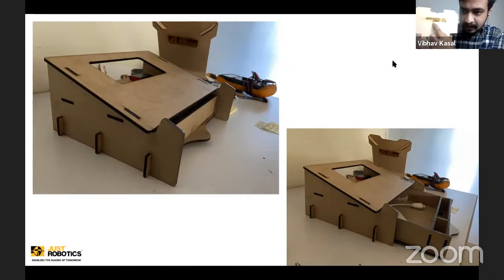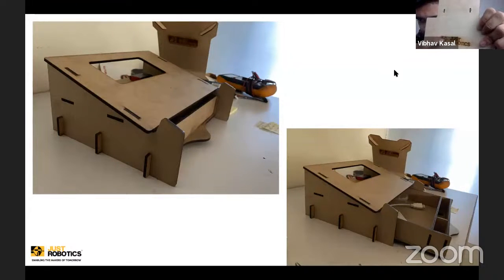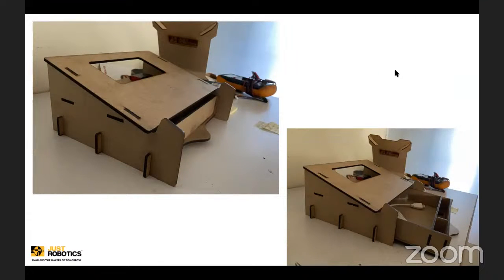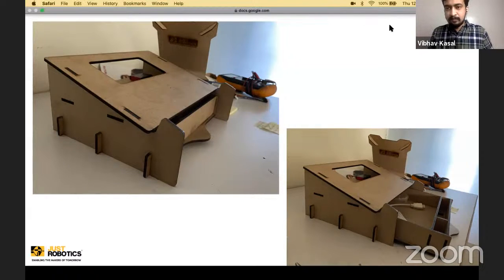I'm doing etching so that my logo comes on this panel, so it looks premium. When we are doing laser cutting or etching, if the infill is little, there are few lines. Here the infill was more, so you can see the depth, and the burn marks have also increased. And sometimes you want these slots to come out of the panel completely, without anything sticking there, so you have to cut it slowly. You can't simply go fast.